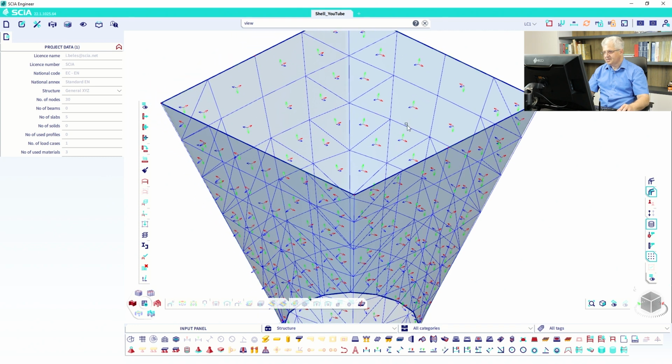So first you see some of them go out of the structure, some of them go in. X is horizontal. This is standard for 3D shells. X is standard horizontal, but I want to have X vertical and I want to have Z going into my structure. This is very good for nonlinear structures, nonlinear calculations, because if you have, for example, a slab, then the Z is going to the top and the surface support is on the bottom.